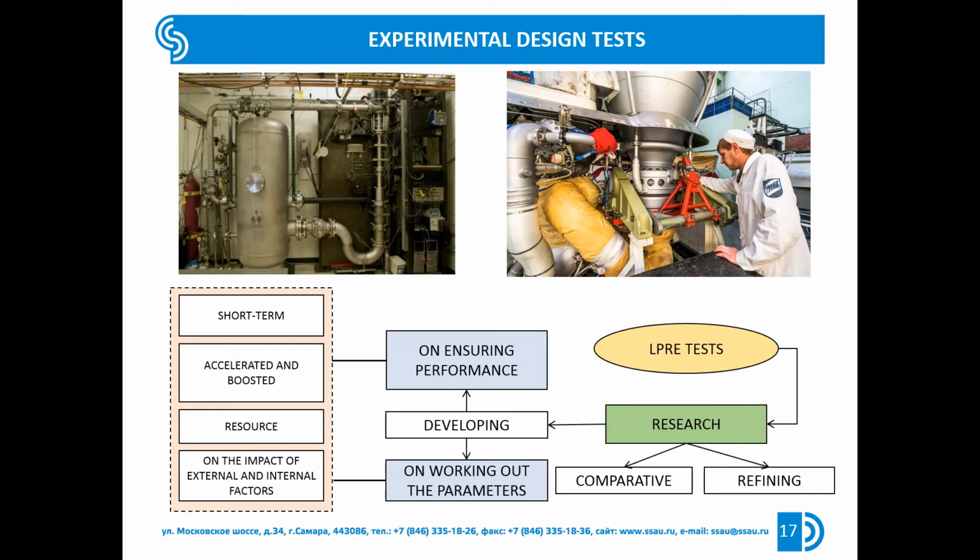To eliminate the influence of uncontrolled random and tolerance variations in setting accuracy, which might lead to failure to reach the target level of the parameter under test, tests are carried out with values of external factors exceeding those specified in the technical specification. This excess may be up to 15% or more of the nominal level.